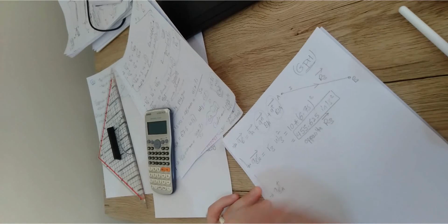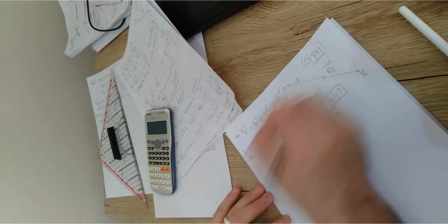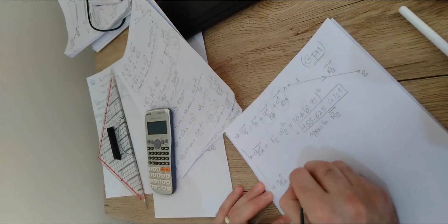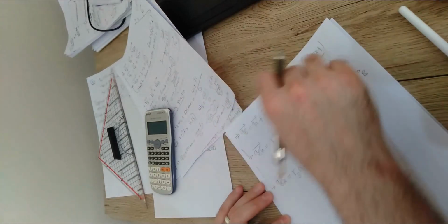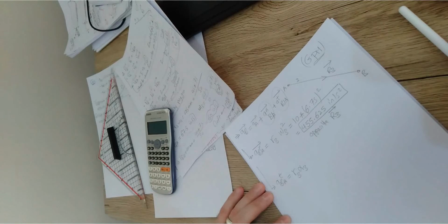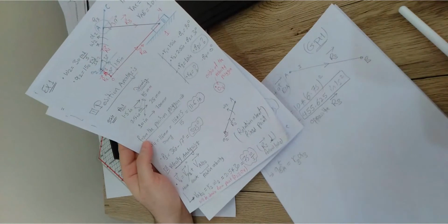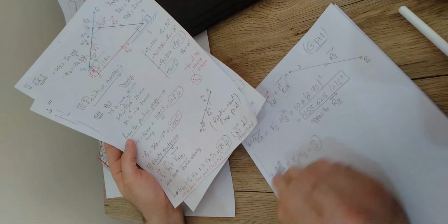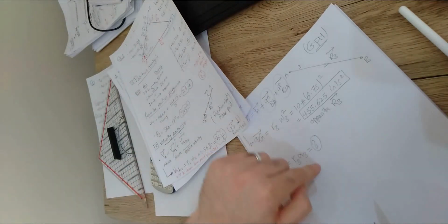A B relative to A tangential. How much is it? If I ask you how much is B relative to A tangential, the formula should be R alpha. But which R, which alpha? It should be R3 alpha 3. Why 3? Because I'm talking about length number 3. R3 is already given as 10 inches up here, right? But how much is alpha 3? We have no clue. Alpha 3 is unknown, so this is the first unknown. And remember that for the acceleration analysis, we are limited to just 2 unknowns. This is the first one of them.